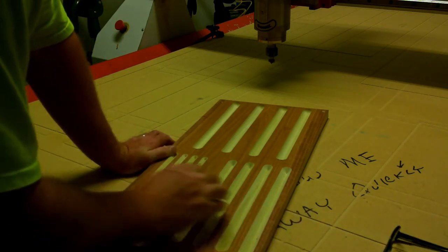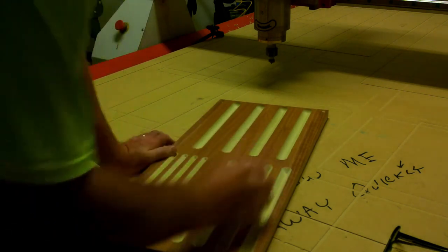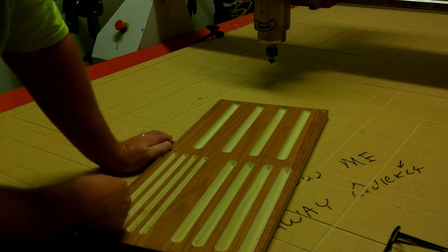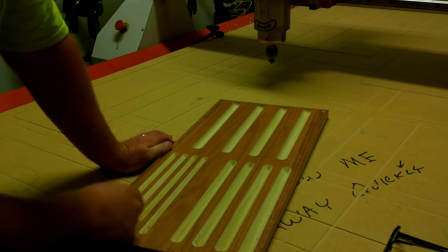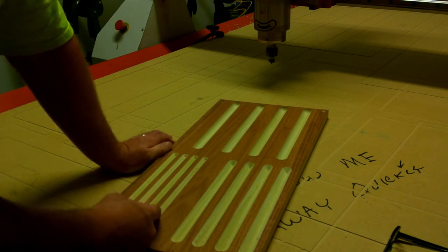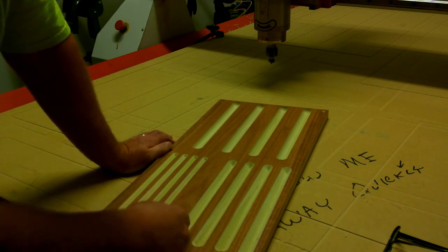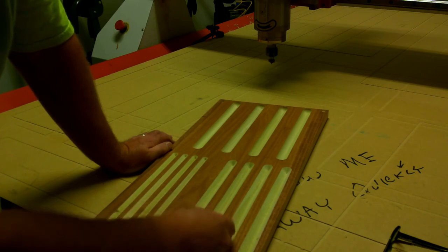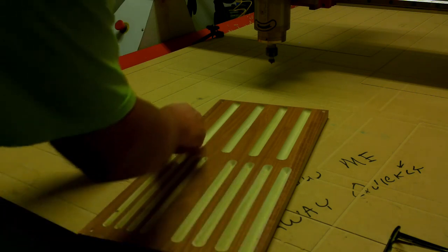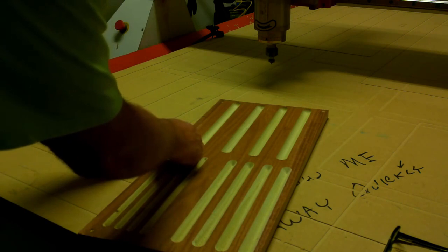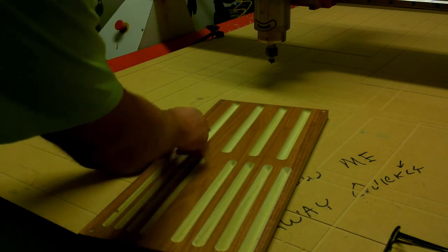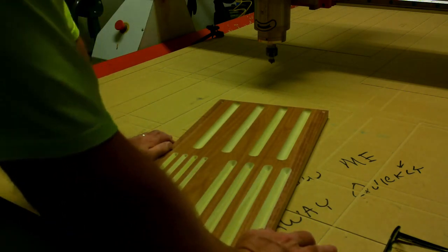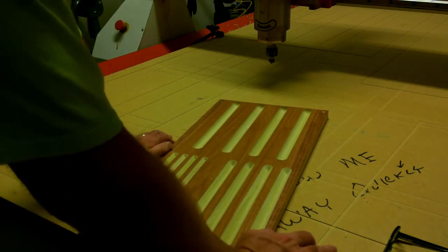4 different speeds for 3 different bits. Okay, this is a pointed round over bit starting at 12,000, 14,000, 16,000, and 18,000 RPM. This is a 90-degree V-bit starting at 12,000, 14, 16, and 18. And this is what's sometimes referred to as a core box bit or a round over bit, and 12,000, 14, 16, and 18. Now, if I were to judge just overall by glancing at the quality of the cut,